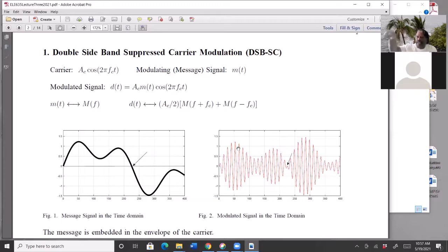Then it goes to the peak, comes back, and starts dropping from the peak. I will show you the diagram later. That will happen if you have the appropriate capacitance. If your capacitance is too small, from the peak it will fall all the way down to zero before rising. But you can adjust the capacitor so that from the peak it decays slowly and meets the next peak a little bit down from the peak. Then it will go up to the peak, then start dropping again, and it might meet the next one.